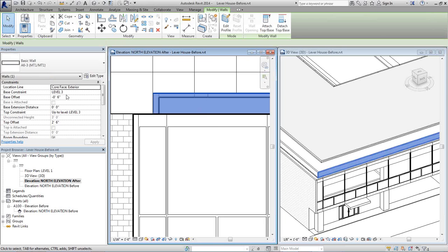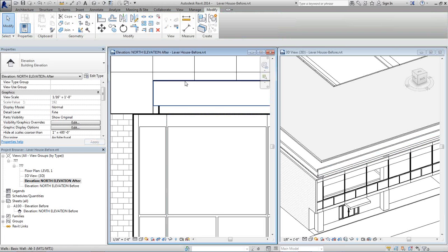If this wall moved in space, so let's say it started somewhere different and it got taller, what's nice is that you've affected that line and it stays the same. Now of course if you delete this wall or you make a new wall, that doesn't apply. But as long as that wall stays the same, and maybe if it moves, you get a lot of value out of using this line work tool.